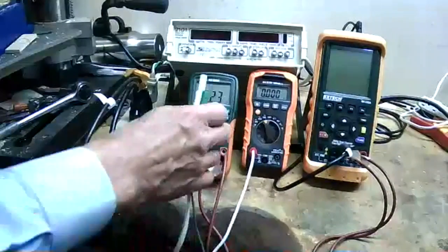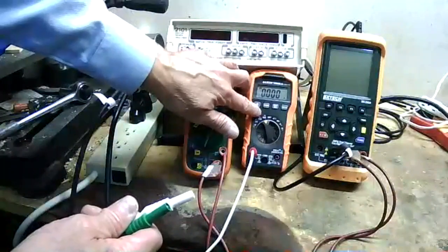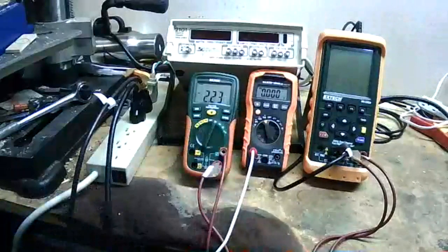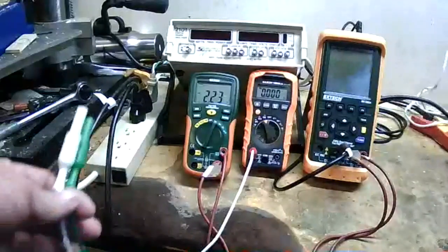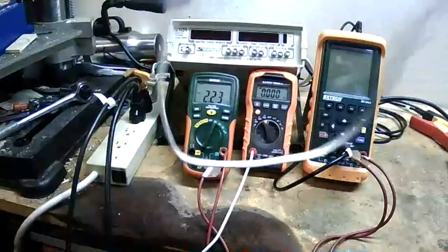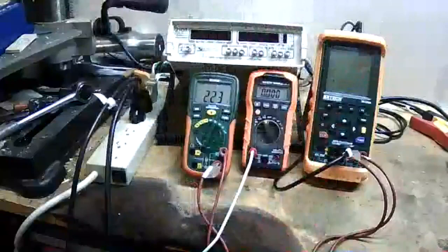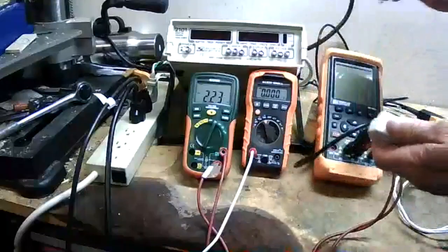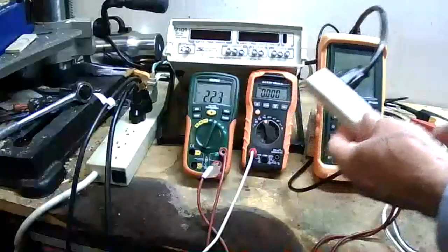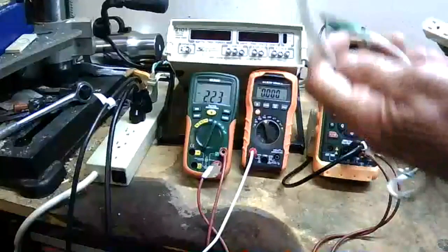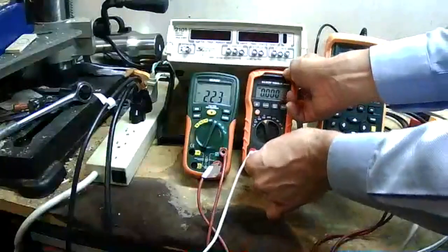It's an auto-ranging multimeter, but you set the AC or DC from this button. This is a new multimeter. So that's the energized conductor. Then I have the other part of the extension cord, also with shrouded leads on it, and I will plug the drill press into this. The drill press is plugged into that. The energized conductor from this will be plugged into the common on the multimeter.